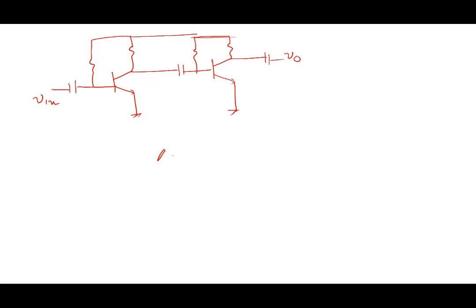So you want AV0 of, he wanted AV0 of minus 50. Well, this becomes a little bit of a problem if he insists on minus. Are you seeing? If the person insists on minus, the first stage gives you what? 180 degree phase shift. Next stage also gives you 180 degree phase shift. Total phase shift becomes 0. But I think by and large, the minus would not be such a problem. Okay, so let's say gain is 50. AV0 is 50. Now what will you do?